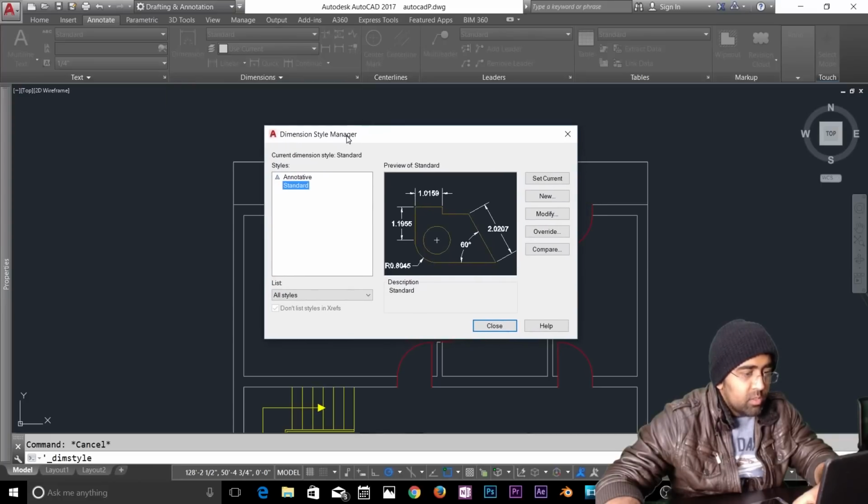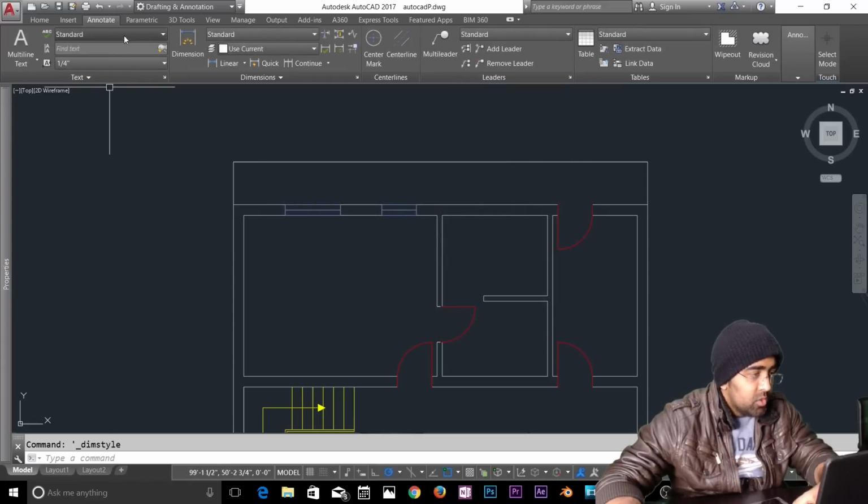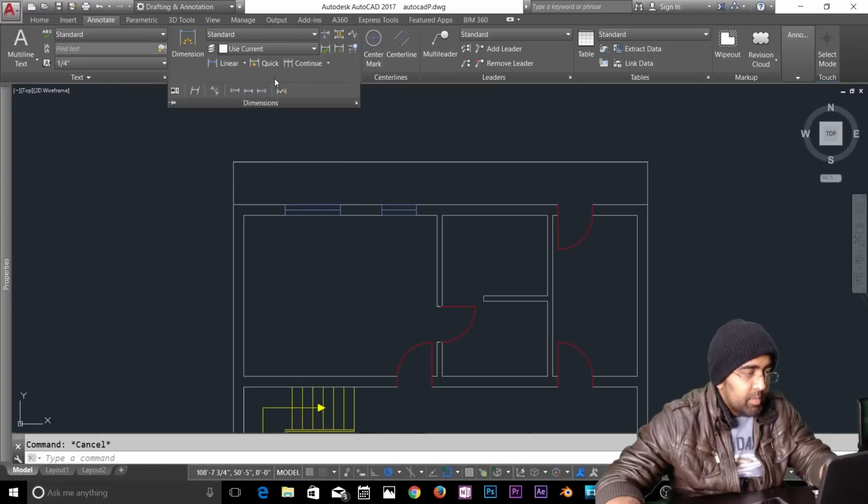That's what I was looking for, but you could set up your dimension here. I can show you there. So you can change that to text, and you can change the text size, which is 1.4. Let me just find that. Okay, you click here and then scale it up. Alright, but let's go to the dimension style here.